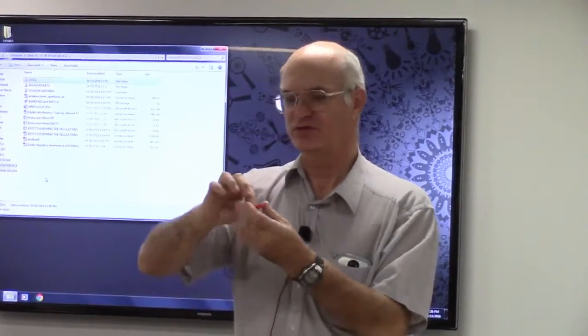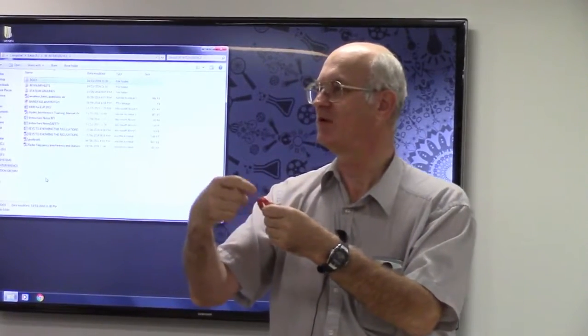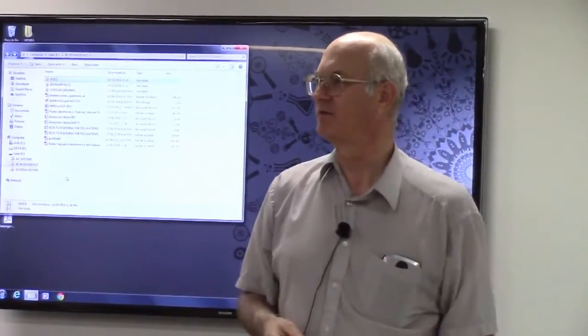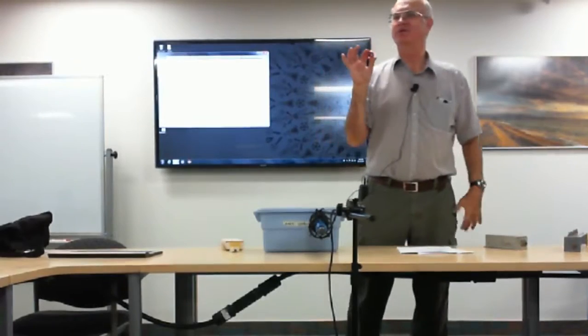So if you take that a little bit further, one of the simplest ways to take care of audio RF in a common stereo system, or a person's home stereo system, is to take a little toroid coil, go right up near where the speakers go into the radio itself, just wrap a portion of the speaker cable around this as much as you want, clip it back in and walk away. That alone will probably end the problem. They're cheap, the neighbor's happy, and done.